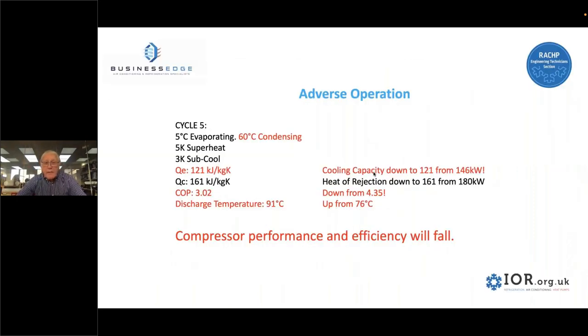So what are the effects now? My cooling capacity has dropped quite considerably, down to 121 kilowatts. Heat rejection is also down. The compressor will really suffer under these circumstances. Moreover, the discharge temperature has now gone up to 91 degrees C.